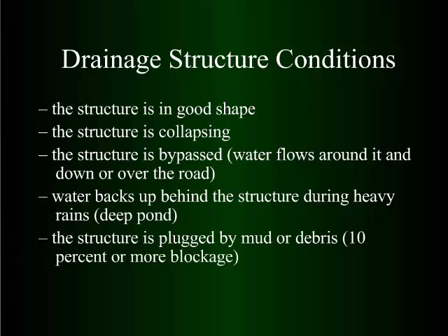And then whether the structure is plugged by mud or debris. 10%, kind of a random number, but if it's plugged more than that, you may want to do some maintenance to try to unplug it. If anyone's ever cleaned culverts before, it's not very fun.